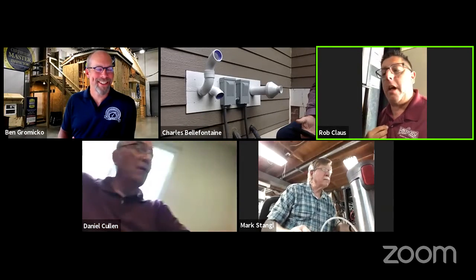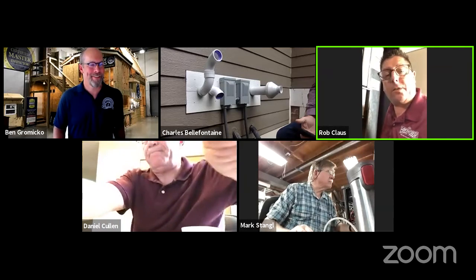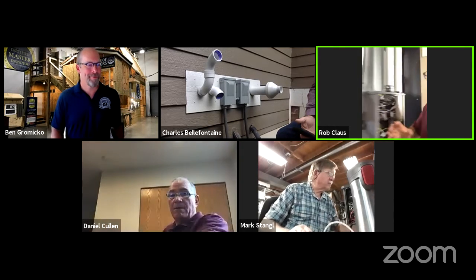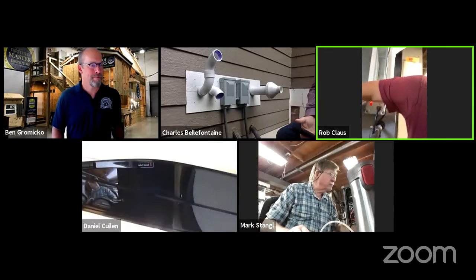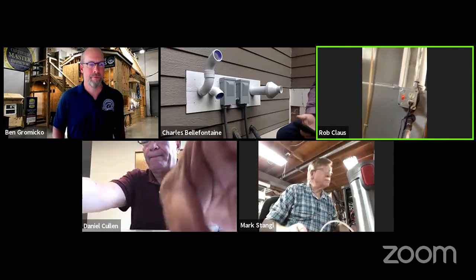It's weird, it's kinky, but it's something that you train your clients to do. They can do this every time they change their furnace filter. Get this thing running, they should be able to touch every square centimeter of the outer wall of the cabinet of their furnace on the three sides that are not the business end of this furnace.